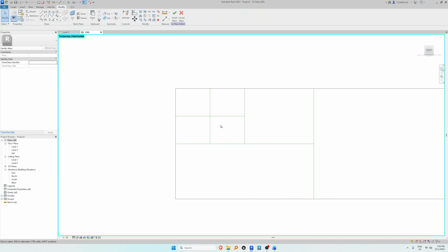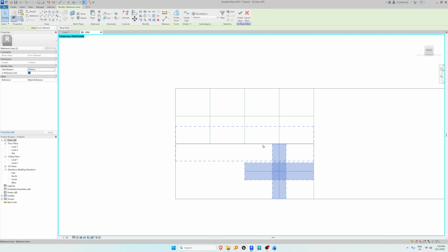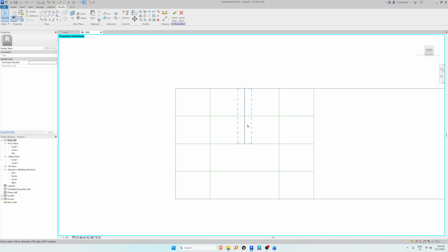So now this will be our center point for our first dowel. This would be the second one. Just select these two, mirror it, press MM, or you can mirror it using this tool. I'm going to mirror it at the bottom as well, and then mirror it on the left. So MM again, mirror on all the sides.